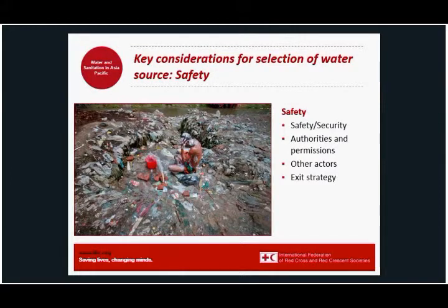Is it possible to fence the site, and store any chemical consumables safely and out of reach of animals, children, and curious adults? Are there likely to be problems with theft? Will byproducts be produced, like settled sludge from water treatment, and how will they be disposed of? Make sure correct permissions are obtained and it is well explained what will happen on the site and how long it is likely to be occupied. Staff operating equipment and handling chemicals need to be properly trained and supervised.